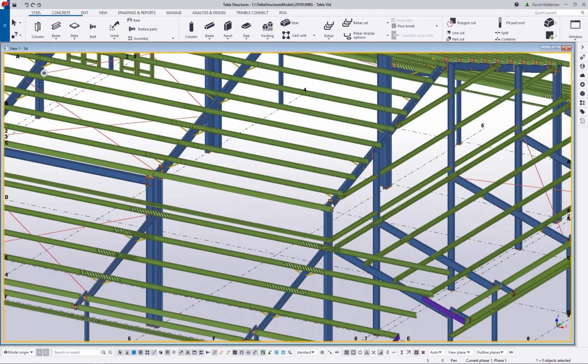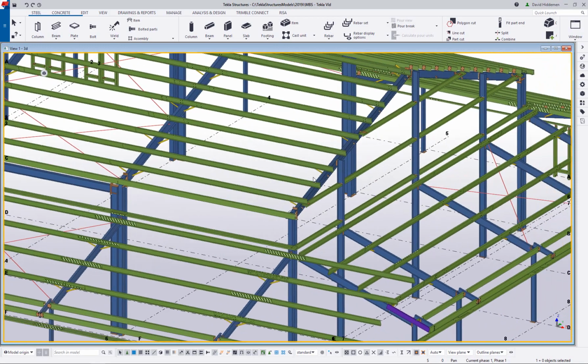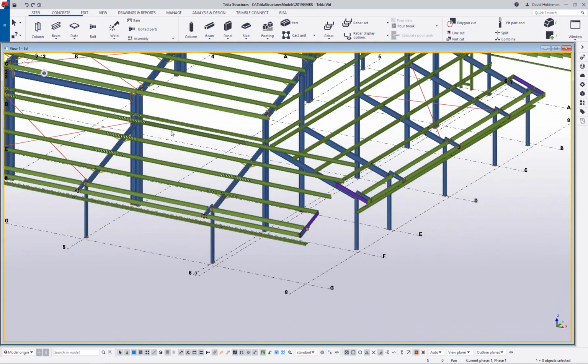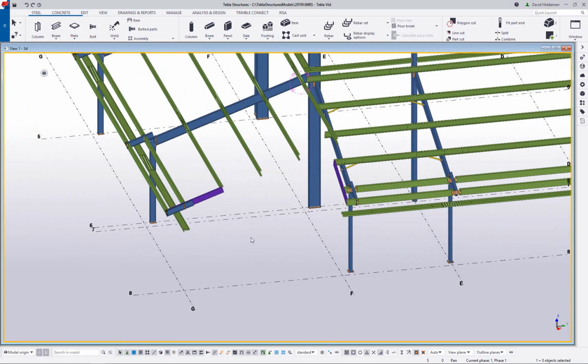If I zoom in here a bit, we can see that the structural members have been brought in, as I mentioned, along with bolts and welds, connection material, flange braces, everything that was designed and detailed in the MBS project. Now, you may also remember that the separate lean-to structures were brought in, one going all the way out to the outside edge and one stopping short. So here in Tekla Structures is where we're going to finish the framing to create that hip condition.